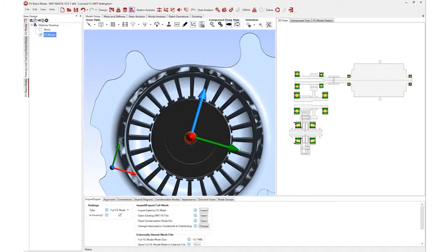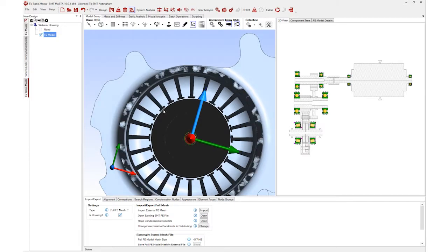So this is the method we normally use. We just go with the teeth, and we're going to connect to those, input our excitation to those teeth. However, do be aware that if you start looking at your MVH results and you start seeing some modes related directly to these teeth, in which you're getting some excitation, just take those with a pinch of salt, as the frequency in which they're occurring may not be completely accurate, depending on the way you've decided to model. Just be fully aware of the method you've used to model and the kind of things you've chosen to do.